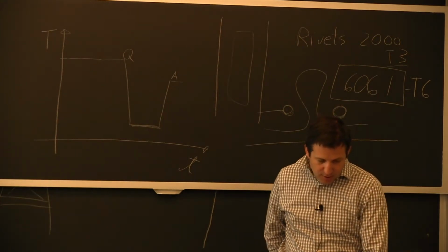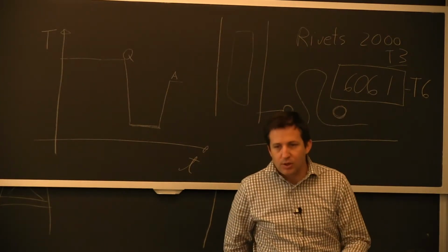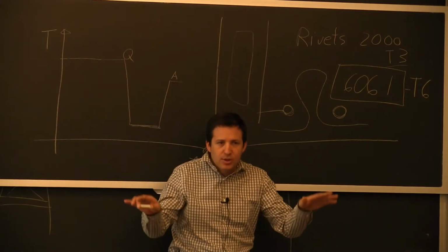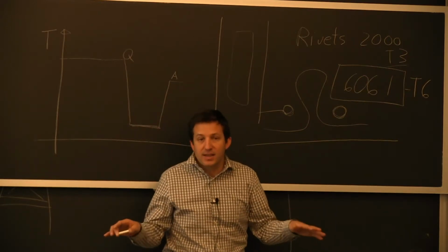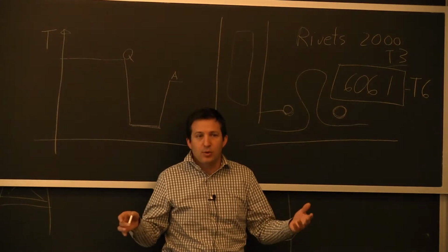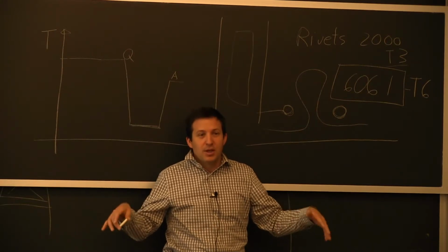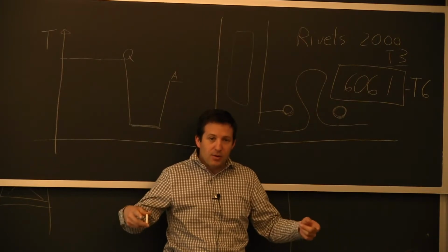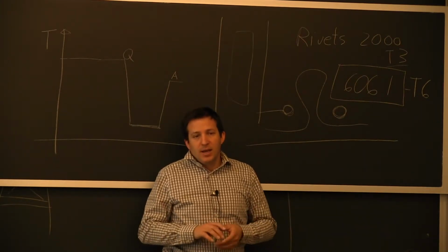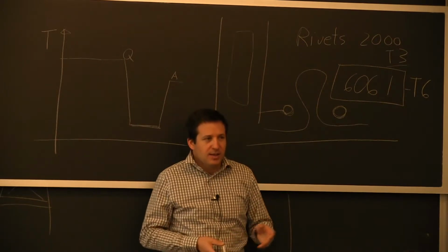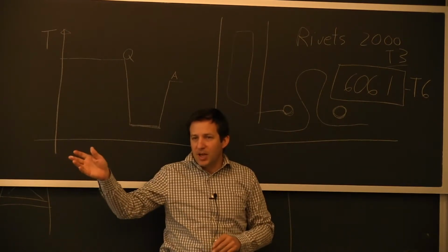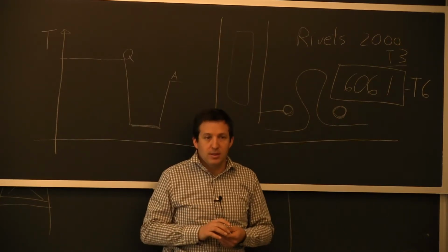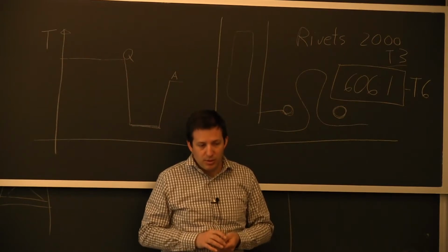Now, going a little higher here in terms of quality control, in terms of aircraft, in terms of wind load, how much deflection of the wing you get, this is very precise data. When they have a model, they have a working prototype, they go and figure out how much the wing is deflecting during use, and they can go back and evaluate exactly what the stress level is. And therefore, in that industry, when they say, this is my stress, this is my capacity, they use a lower factor of safety, because they know better what they are dealing with on both sides of the equation.